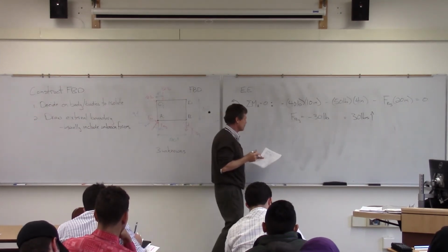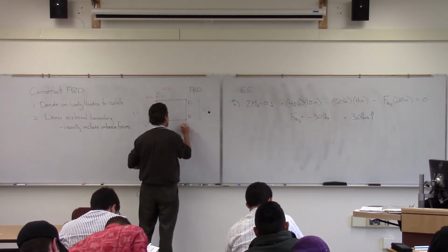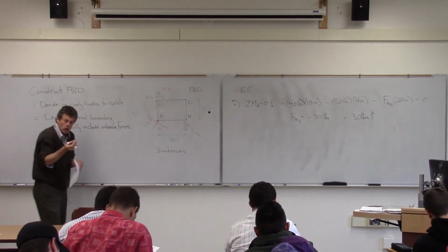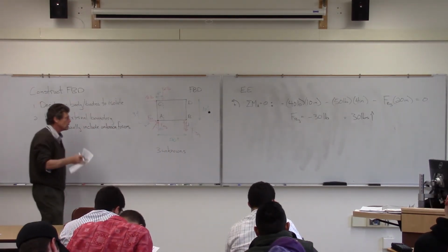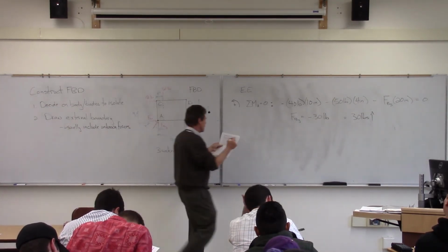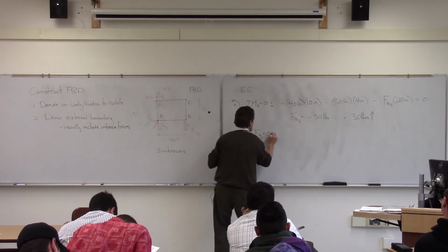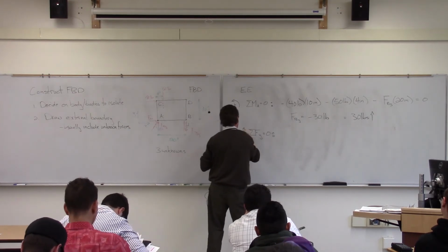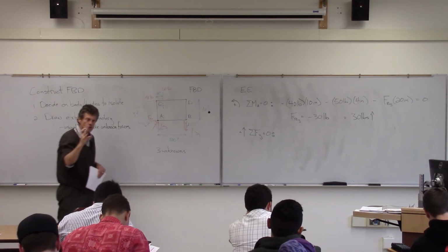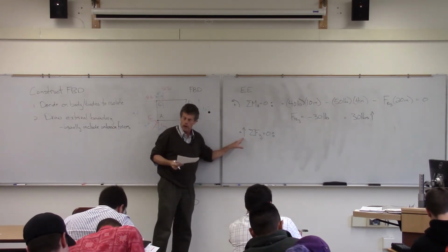OK, so I just solved for that. Once I've recognized that was the wrong direction, I need to make sure that when I do my other calculations, I have it corrected. So go back, fix it. But the nice thing is statics will give me the right direction there. My next step then is choosing one of the components of R. In this particular case, I'll just do Fy, and I'm going to choose the up direction as the positive convention for this equation.